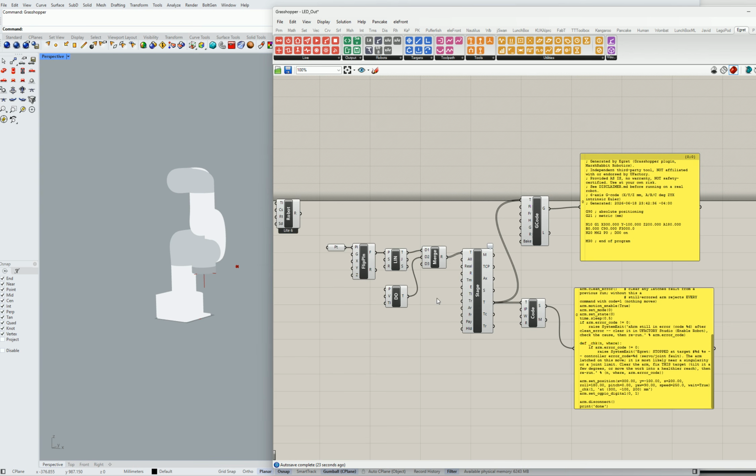I should note that my LEDs share a common 24 volt. I bought 24 volt LEDs. Most LEDs are like 5 volt, so just be aware that you'll need to put a resistor on if you're using an LED, or get 24 volt LEDs, or maybe whatever your load is. Maybe you're talking to a PLC, it accepts 24 volt.